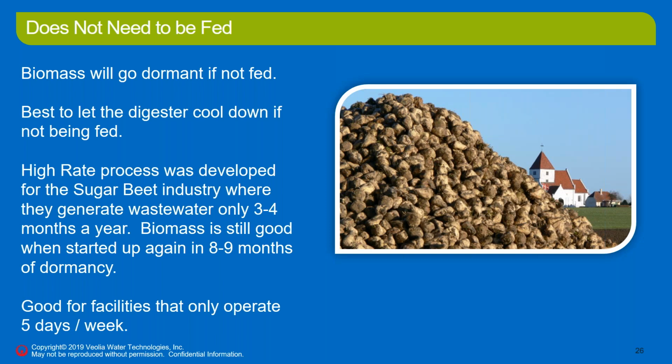Now, you don't need to feed this sludge, and it won't lose activity. In fact, if you have to shut your reactor down, it's best to let it cool down because, again, that activity goes down. It's not trying to eat anything, and it won't eat itself. It won't try to eat other bacteria that's in there.